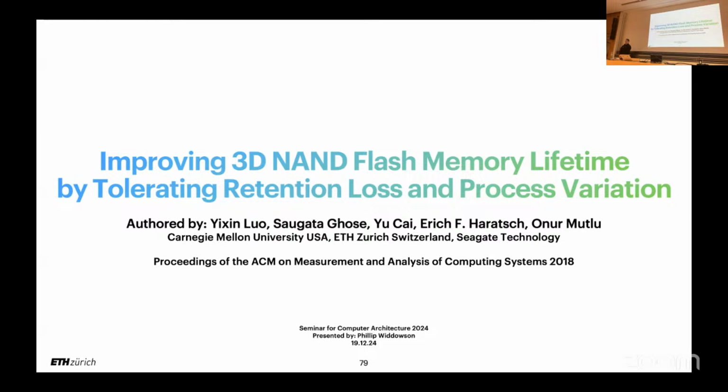I mentioned that I couldn't really find that much research showing that QLC and TLC have a much higher error rate than MLC. Yeah, it's unfortunate. You can find research at the device level. If you go to a conference like IEDM, the Electron Devices Meeting, you will see device-level research where people characterize read disturbance, retention, etc. But at a real system level, research like this is lacking because it's very difficult to get access to the commands with which you can exercise flash, build infrastructure, and get results.